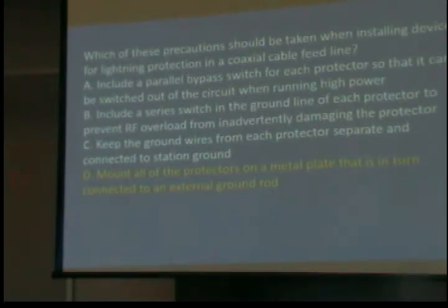Now, I have 11 outdoor antennas, so I've got a little bit of an overkill. If you had one, I would come down, bring the coax in with a lightning protector out there and a ground from it. Does that go actually outside? I just know my DirecTV antenna had a copper wire on the outside. Is that what they do with these too?